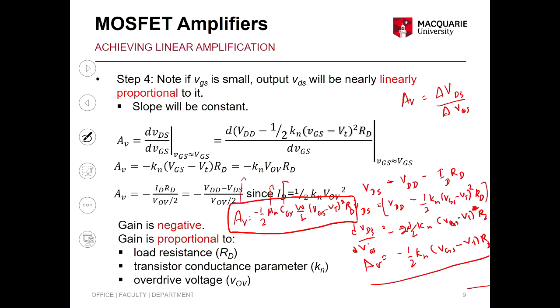The other thing the designer can do is control W over L. Increasing W over L would give you a higher gain, right? So if you use larger widths, when you use 2 by 25 versus 2 by 50, 2 by 50 might give you a higher gain. But you also noticed there was the MCQ. Would it give you the larger gain overall, over all the frequencies? No. When you plot it, it didn't work. So there might be other characteristics that come into play. You have to play with it.